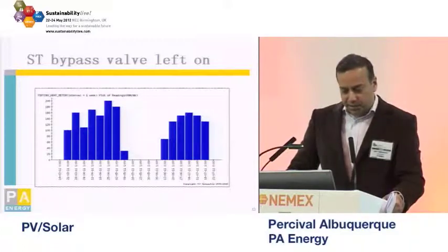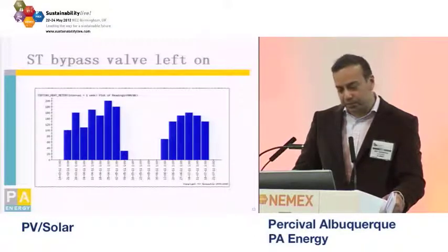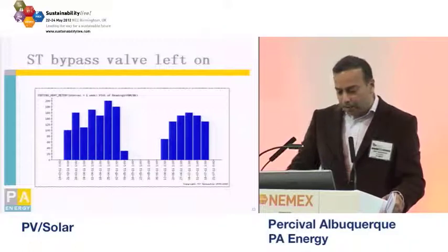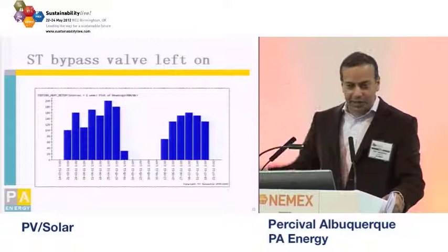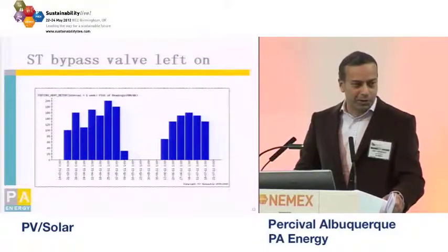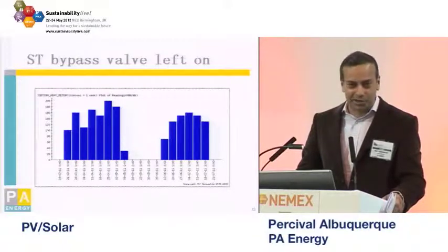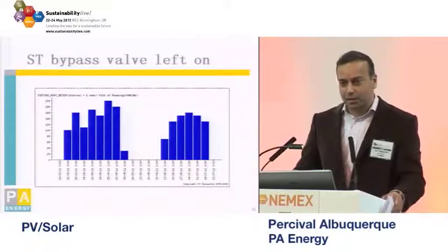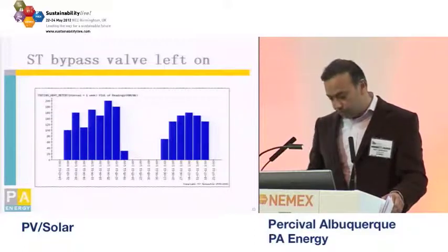This is a solar thermal system. And this particular one can really produce quite a bit of energy. In fact, we had to use a meter that was in megawatts, purely because of the pipe dimensions. And the reason there's that flat line in the middle of November is that at this particular site, the person or the manager who occupies that building was not getting enough water pressure on the top story of the building, and so they decided to shut off or bypass the solar thermal system. So these are the kind of things we pick up, and as a result of this, the customer is going to resolve the pressure issue. So these systems can be sabotaged, not by blatant bad behavior, but just by work practices. So just something to be aware of.